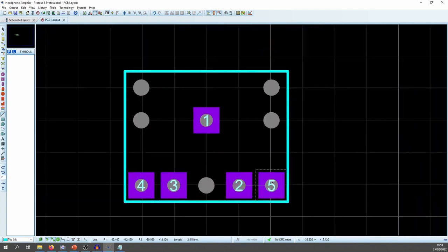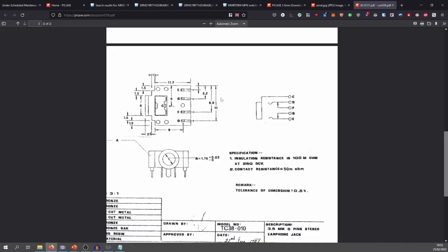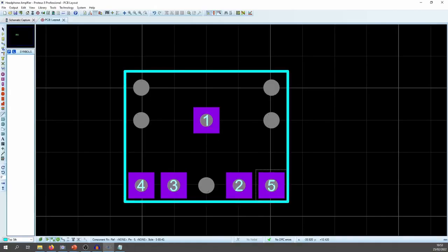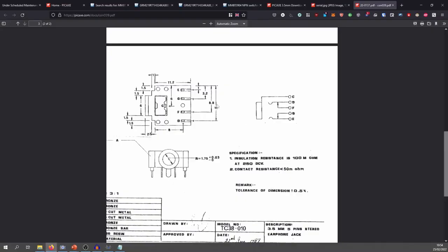Click that. See, it says 2.54. You see that at the bottom? That's the length of this current line. And that's 2.2 between these two pins. But because the hole is quite large on these, I'm pretty sure it's going to work. And then we can do it for this pin to that pin is 7.62 millimeters.